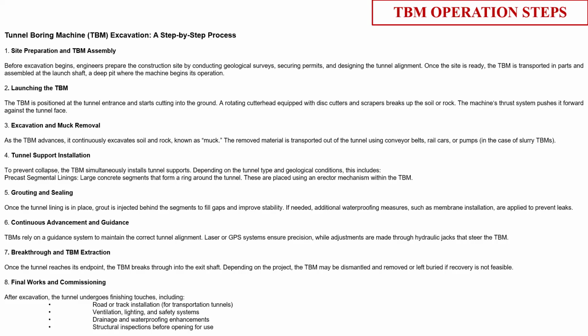So this gap is mostly filled by grout, and the grout acts as a backfill material as well as a packing material. So there is a complete bonding, a complete interface, filled by the grout between the ground and the TBM segment. That is called the primary grouting. After the primary grouting, if you see that water is still coming through the grout sockets or the bolt pockets, then we go for another round of grouting, called the secondary grouting. These are mostly backfill grouting, so you are not grouting at a very high pressure.